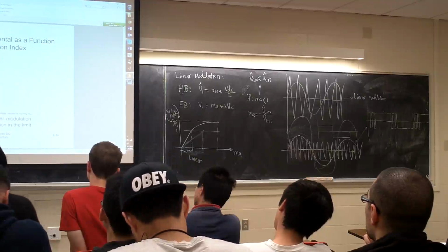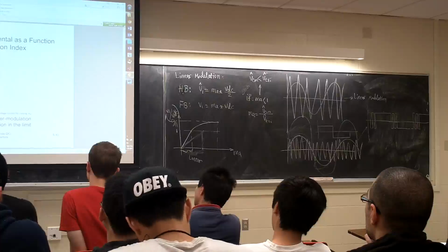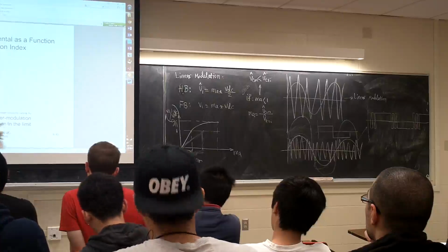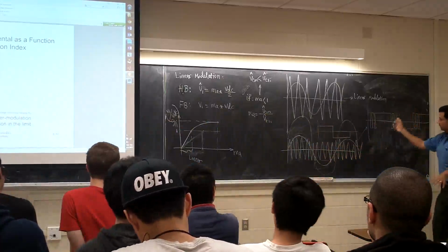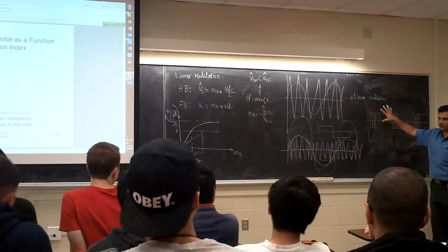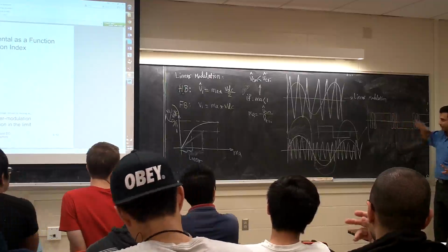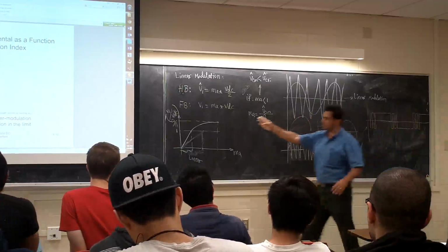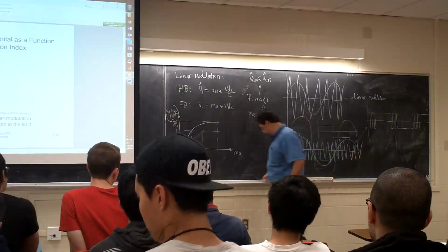So basically you have the linear part, and this we call overmodulation, right? Still in the overmodulation they're going to be like this. Sorry, you guys cannot see from there. Here there is some chopping on the side, but in the middle there is no chopping, right? This is the overmodulation part. And after we get to this point, it's going to be a square wave.